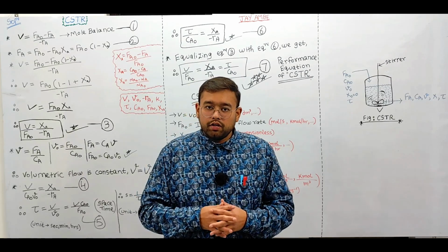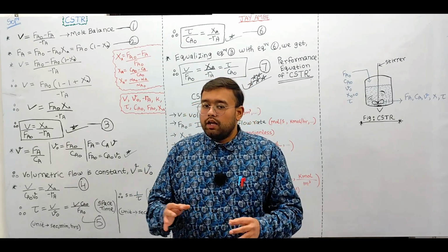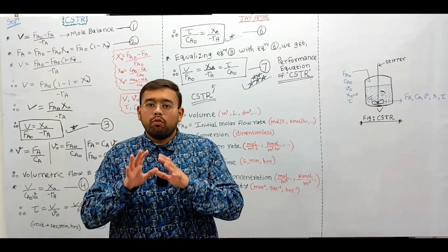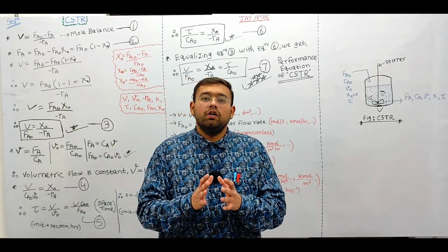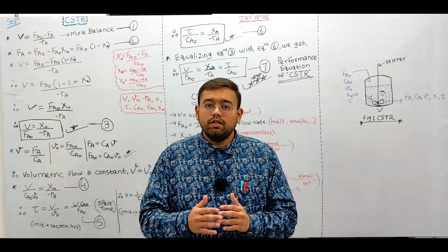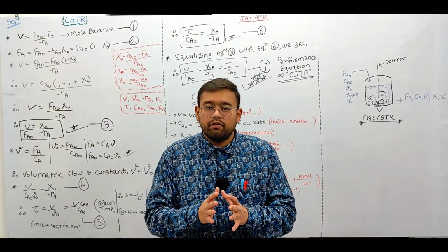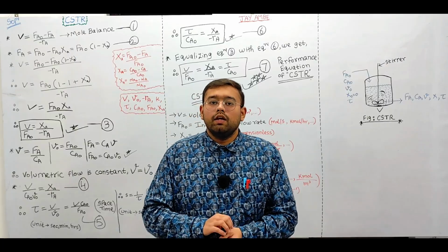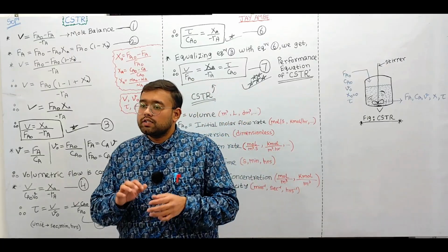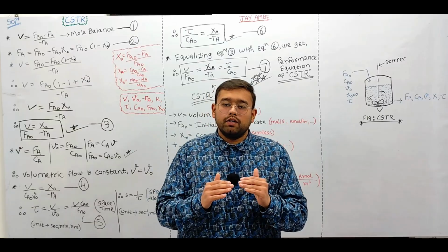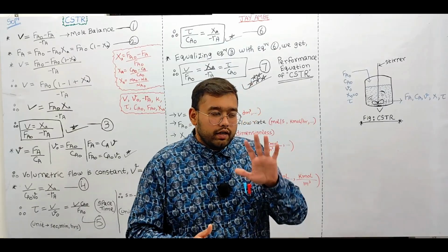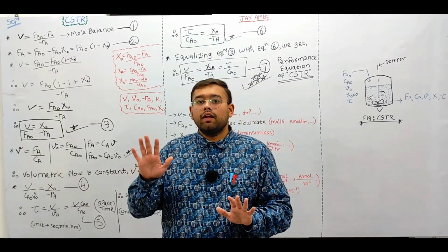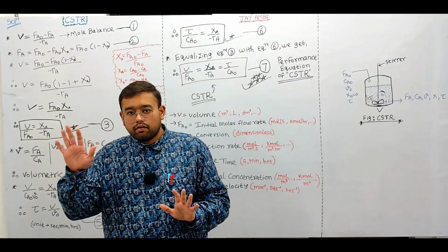But as a chemical engineer, we need to estimate how large a volume of reactor is required in order to achieve the desired conversion and have the reaction complete efficiently, right? So understanding the performance equation will help us use the reaction kinetics in order to design the reactor.